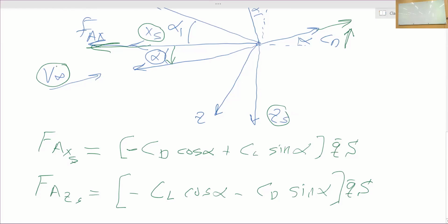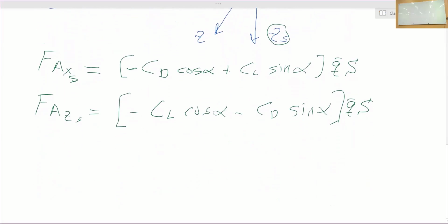In the lateral directional direction, we don't have to worry about this because alpha is in the longitudinal forces and moments. And of course, the moment is easy because it doesn't matter whether we're shifting an alpha or not, the moment is still calculated around the y-axis.